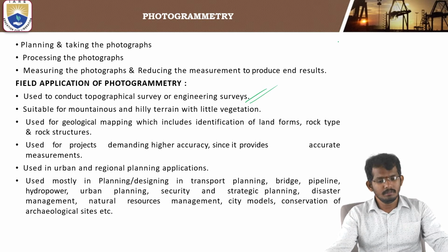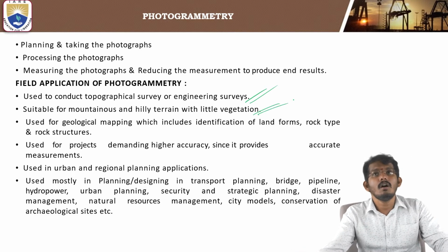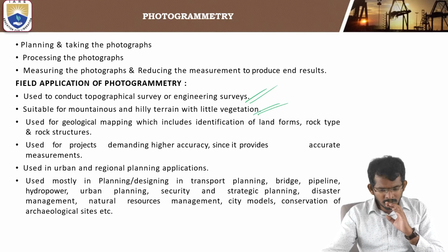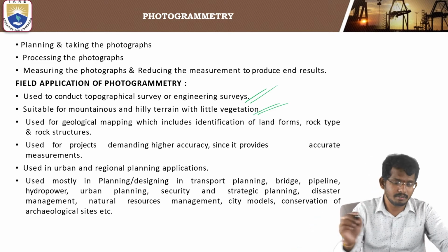Suitable for mountainous and hilly terrain with little vegetation. So on hilly and mountainous terrain where we have slopes, we cannot go there and capture the photograph. So using this technique of aerial photogrammetry, we can capture the photographs. Used for geological mapping, which includes identification of rocks and minerals, rock type and rock structure.